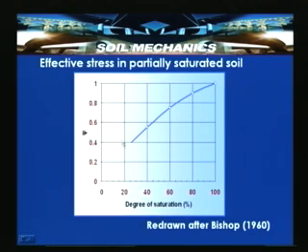So, this chart or graph shows the variation of psi, a fraction or constant, with the degree of saturation. You can see here that for 100% saturation this value tends to 1, and for 30% saturation the value works out to be around 0.4 or so. So, for intermediate partially saturated conditions this value can be obtained to compute the total stress, which is equal to effective stress plus pore air pressure plus pore water pressure.